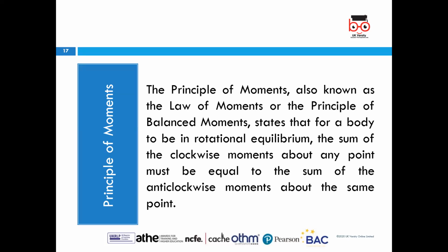This is an engineering principle, also known as the law of moments or principle of balanced moments. It states that for a body to be in rotational equilibrium, the sum of the clockwise moments about any point must be equal to the sum of anti-clockwise moments about the same point. If the sum of the clockwise moments about any point is not the same as the sum of anti-clockwise moments about the same point, then the body will not be in rotational equilibrium.